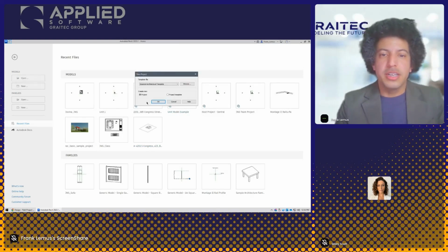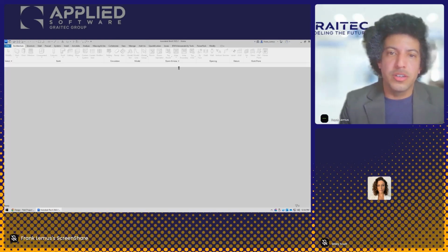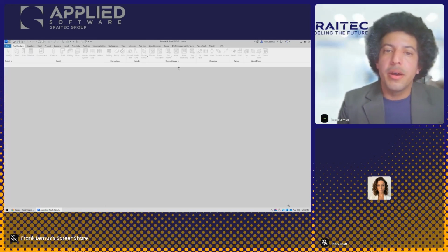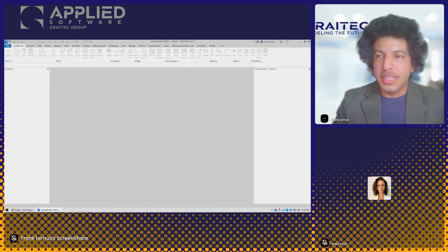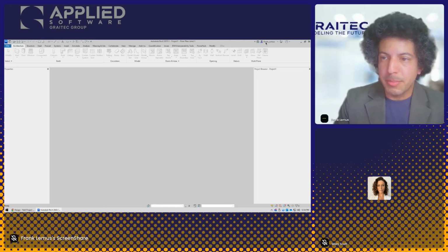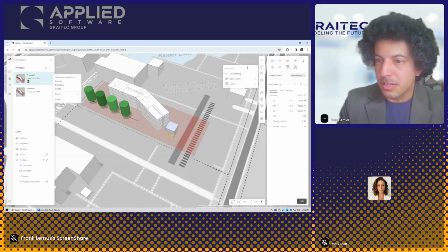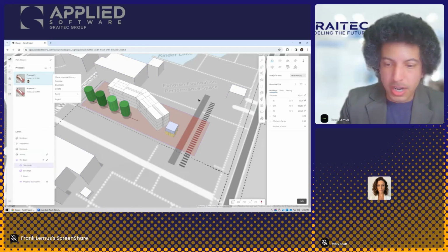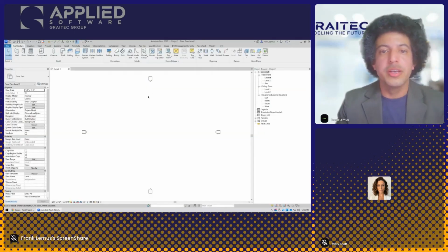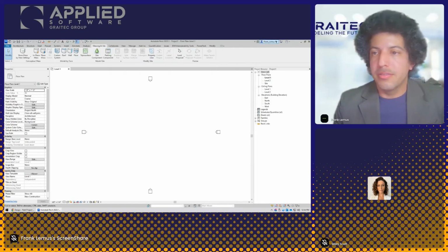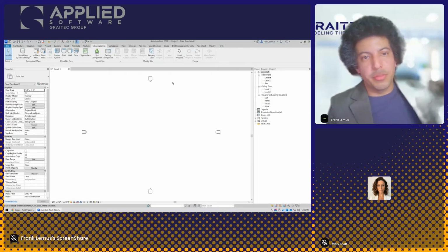I'll start a new project. It has no knowledge of this project. You don't have to do anything to connect it because it's in the cloud. It's basing it off of your username. My name here is Frank Limas, and I'm also signed in as Frank Limas in the browser for this project. It doesn't show me here, but that's the way it works. So when I come over here, Revit says, hey, Frank Limas has uploaded the proposal.